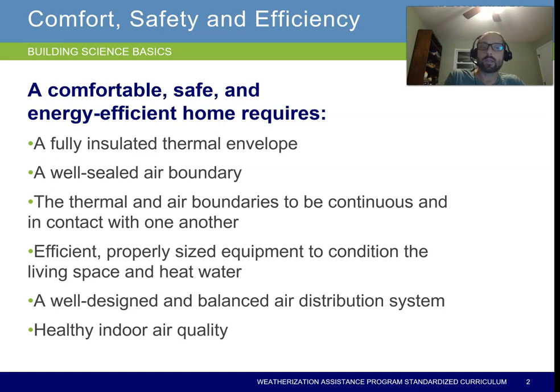That's different than the air boundary or the pressure boundary, which is the same thing as the air boundary, which needs to be tightly sealed. So the air boundary prevents air from moving. The thermal boundary, the thermal envelope, prevents heat from moving. Very important but subtle difference. They can be the same, but it depends. They're not always the same.